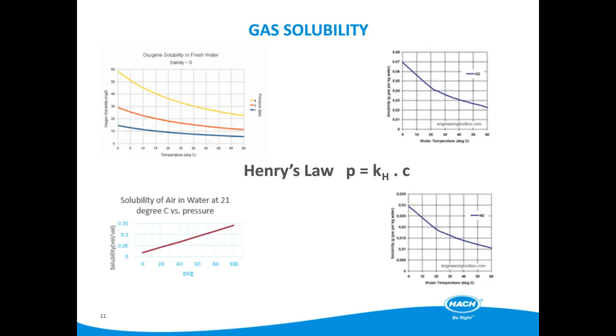As stated previously, the DAF process is purely a physical process for the removal of solids from the waste stream, and no biological treatment is intended within the process. So you would think the relative solubilities of nitrogen and oxygen play no part in the efficiency of the treatment process. However, as oxygen has a higher solubility in water than nitrogen, as can be seen from the graphs on the right-hand side of this slide,